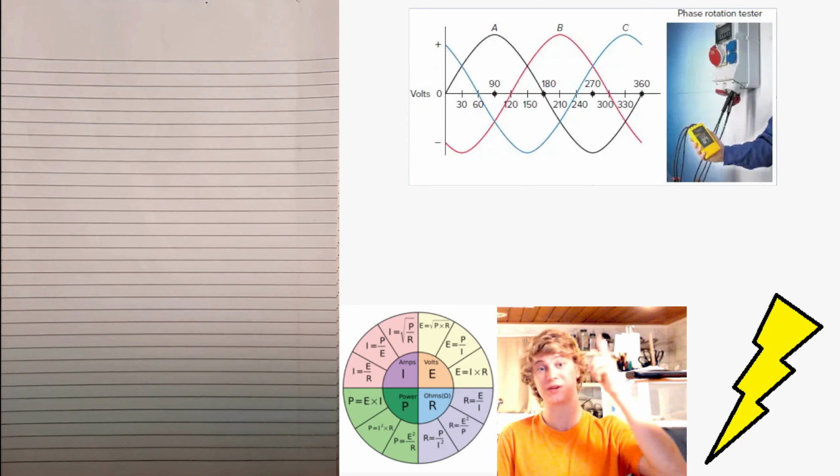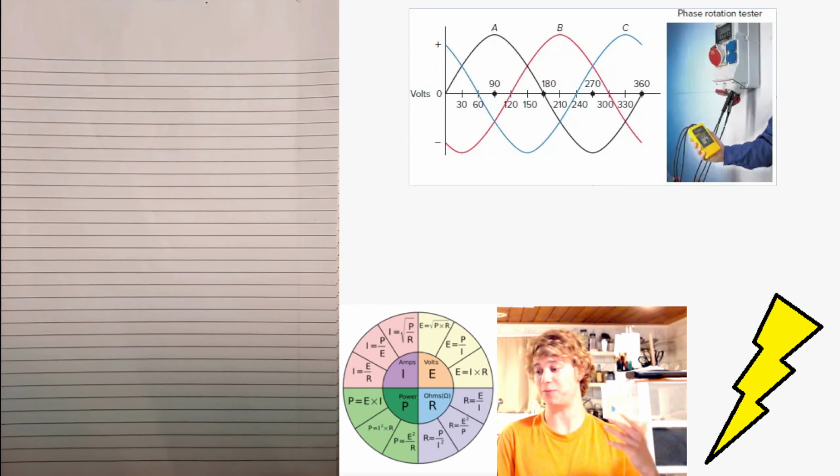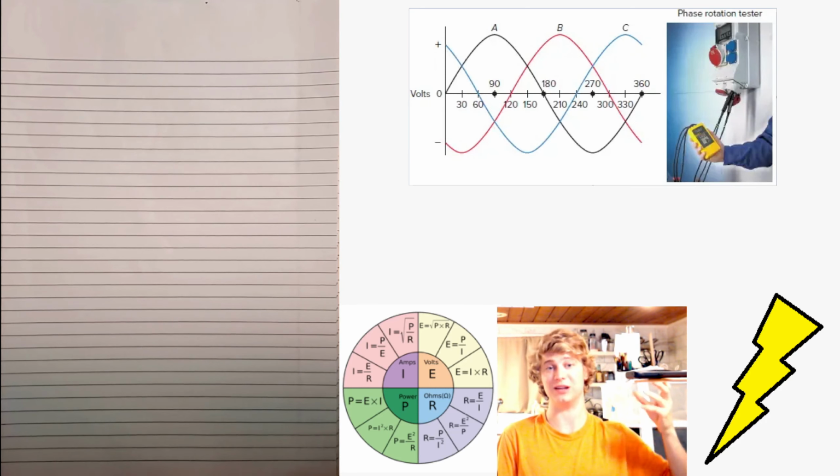Okay, so we see the 3-phase waveform graph up above. We can see that phase A starts to rise in a positive direction at 0 electrical degrees. Once it gets to 120 electrical degrees, phase B begins to increase in a positive direction from its 0 point, or the 0 crossing. 120 electrical degrees later, so we can see at the mark 240, phase C now begins to rise. So we can see where these are 120 electrical degrees apart because the alternator has 3 sets of coils that are positioned 120 degrees apart.